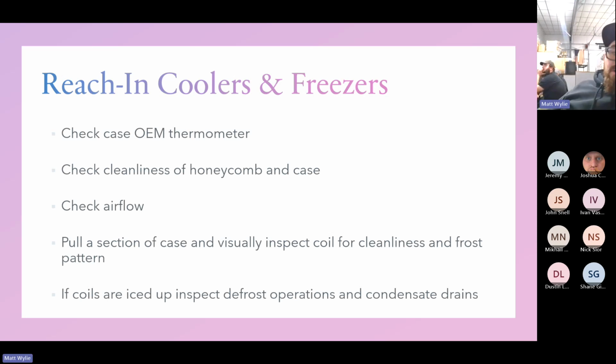The coolers. Basically, on your box stores and grocery stores, check your honeycomb in the cases. Check the airflow. If you can, pull a section of the case and visually inspect the coil for cleanliness and frost pattern. Certain stores wash their own coils. Costco, I know Costco does. I don't know about Smith's.